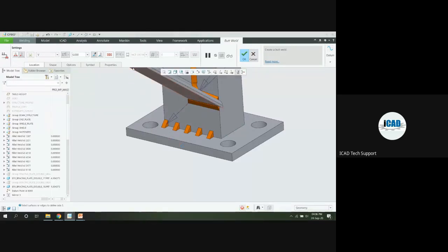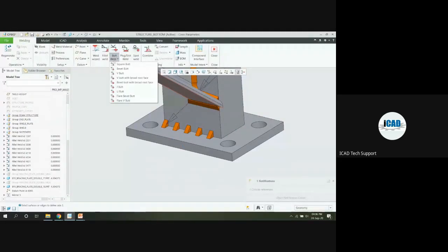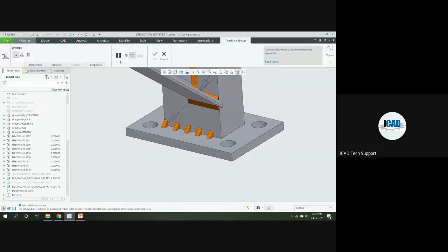If you want to use these different types of welding, butt welds, square weld, bevel weld, we need to set these differently. And here is some combine option available. You can see for the references, reinforcement material if you want to add, and references other side.